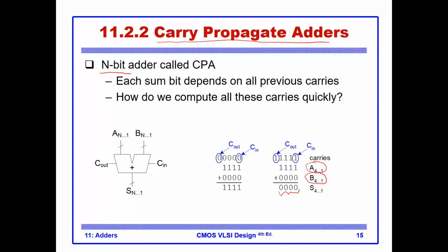Okay, so let's take this computation. We are assuming that we have a carry in of a 1, right? So we add this to the first bit of A and the first bit of B. This addition happens to be a 1-bit addition because we're going to add three 1-bit digits, and we will get a sum and a carry. So 1 plus 1 plus 0, we will have a sum of 0 and a carry to the next position of 1.